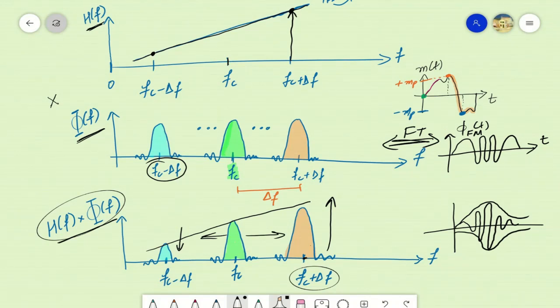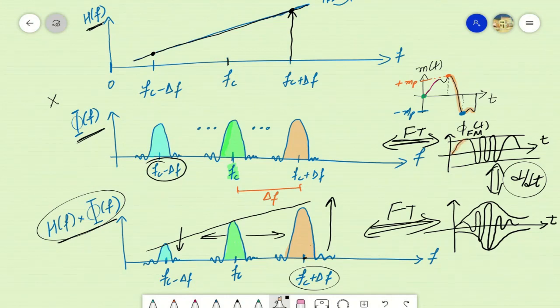Variations in its peak amplitudes are being caused. So the Fourier transform of this signal can be represented by this signal. So this is the exact operation which the derivative operator was performing. The derivator was translating the frequency fluctuations into amplitude fluctuations of the derivator's output signal, which is exactly the operation which a filter with this response is providing.